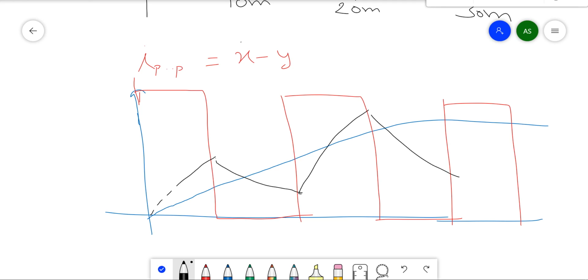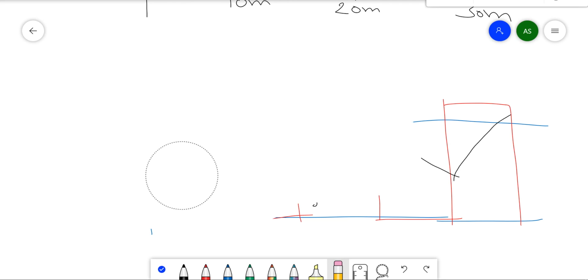You see, this value of X and Y will be changing according to the DC component, because DC is nothing but the average value. Okay, so you can see this here, this is X, this is Y, this is Z. Now here X and Z will not be equal, because the DC component of the current has not reached its steady state till now. But in our case, in this particular problem, the DC component of the current is already reaching steady state very quickly.